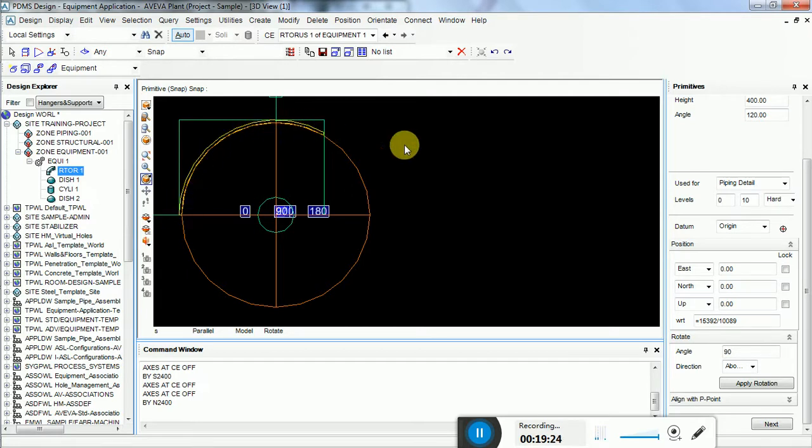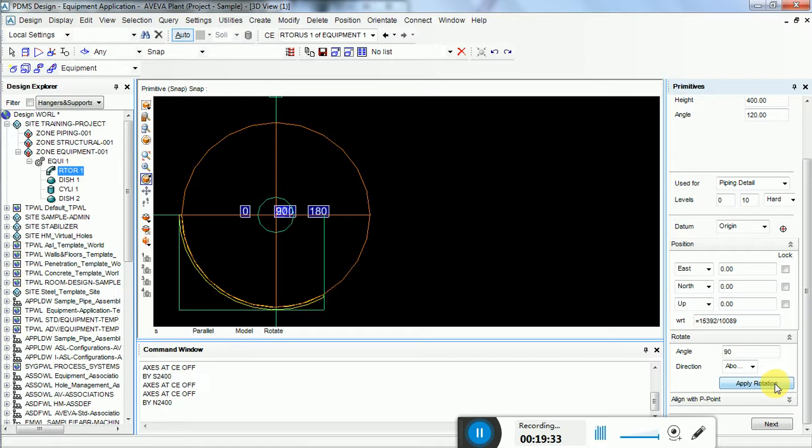these yellow lines. Now again you have to rotate. First, make sure of the rotation. Yeah, this is the okay rotation. Give 30 because we gave 120, and for 180 degrees, 180 minus 120 is 60 degrees, so 30 and 30 remain. So 30 here, 30 here, and 120 will be comprised here. Okay, apply rotation.